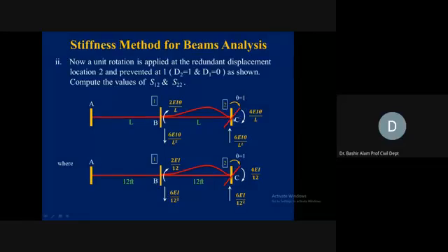C is becoming our near end, so 4 EI theta divided by L, and in the same clockwise direction this moment is generated. Far end, which is our end B, again you see here 2 EI theta, half of this amount, in the same clockwise direction, and this is the balancing couple. Now fixed support, so if we are not showing these rotations and vertical reactions, the moments and the vertical, it means those quantities are 0 here in this manner.